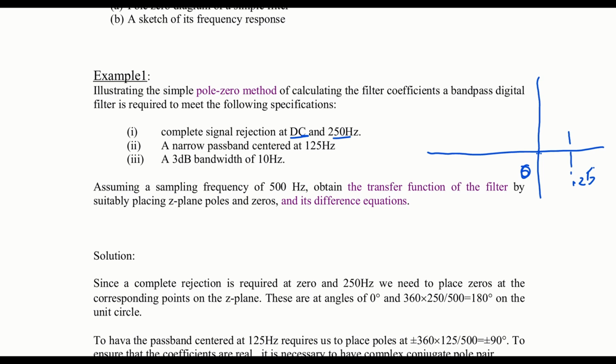The 3 dB bandwidth is more or less the frequencies at which, when you see, the filters are not ideal, okay? So when we are judging the filter quality, we usually use what we call the 3 dB bandwidth, right? And beyond the 3 dB bandwidth, the filter will attenuate by more than half of its power, right? That's the whole judgment procedure.